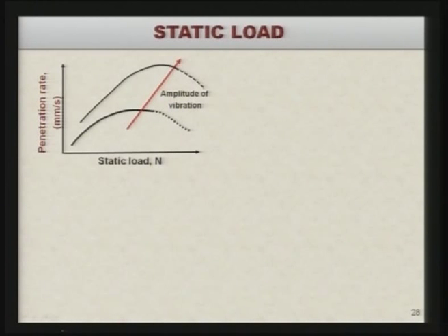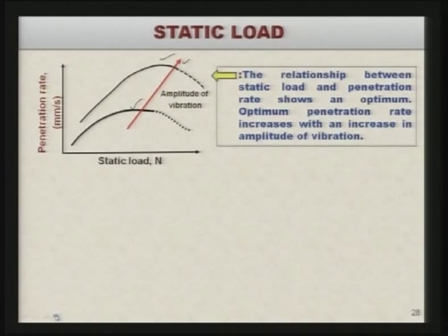Now, static load plays an important role, as we can see over here. As static load is increasing, the penetration rate is increasing in terms of millimeter per second, but beyond a certain value, as you can see in both the cases, it starts decreasing, and as the amplitude of vibration is increasing, the penetration rate is increasing. The relationship between static load and penetration rate shows an optimum value. Optimum penetration rate increases with an increase in amplitude of vibration. This also can be seen, that this optimum value is higher for higher amplitude of vibration.